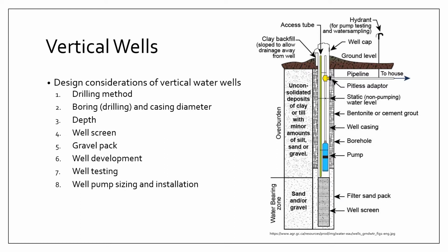I'm also expecting you to read a little bit on the chapter on groundwater well development in the book of Sterret, which is titled Groundwater and Wells. It's a classic textbook, and most of the details that you need in order to properly develop a well or groundwater resource are in that reference. Now, anyway, let's focus on the design considerations of vertical wells.